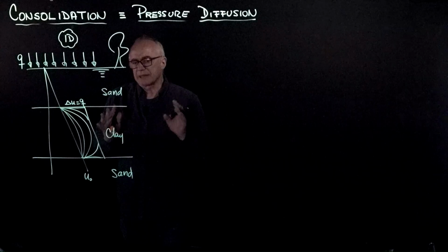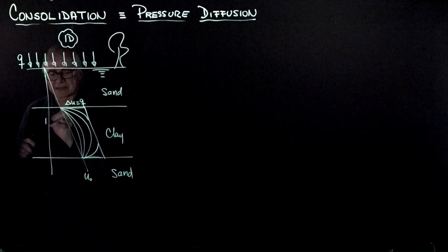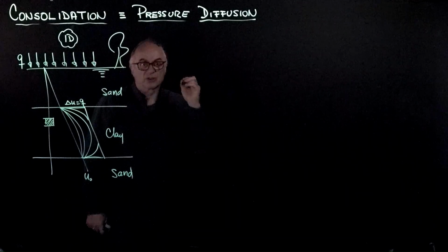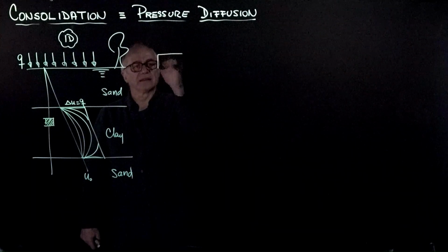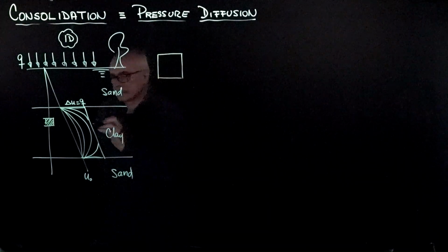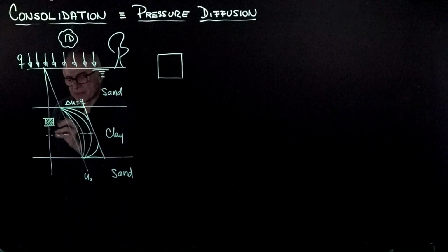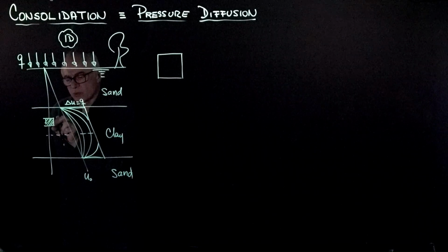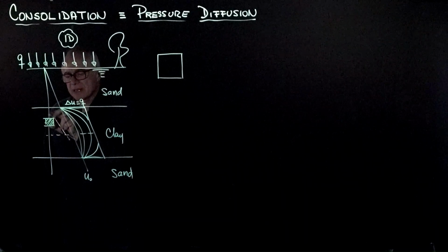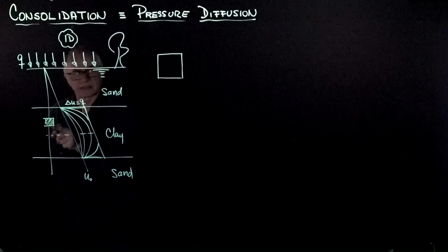In order to understand this a little bit more carefully, let's consider an element at some elevation in the middle of this clay profile. So we are actually looking at this element at a certain depth Z, and we realize that the water, let's draw the center line here, the element at the bottom is squeezing, and the water that is escaping is moving through the upper element, but the upper element is also squeezing, and so there is more water coming out of this element than the water that came in.